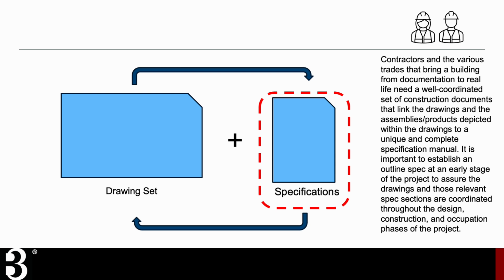So this is where the specification manual adds a ton of text-based information into the way that a project team accurately and completely portrays their design intent. Whereas the drawing set really provides dimensions and the overall coordination of items, the specifications manual is where the project information and the performance of those products, along with the way that they need to be installed, is specified and laid out.